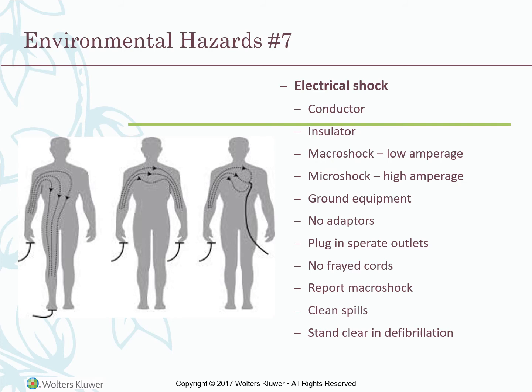Discourage clients from resting electric hair dryers, curling irons, or razors on or near a sink that contains water. Do not use a machine that has a frayed or cracked cord or a plug with exposed wires. Grasp the plug, not the cord, to remove it from an outlet. Do not use extension cords. Report macroshocks to the engineering department. Clean liquid spills as soon as possible. Stand clear of the client in bed during cardiac defibrillation.